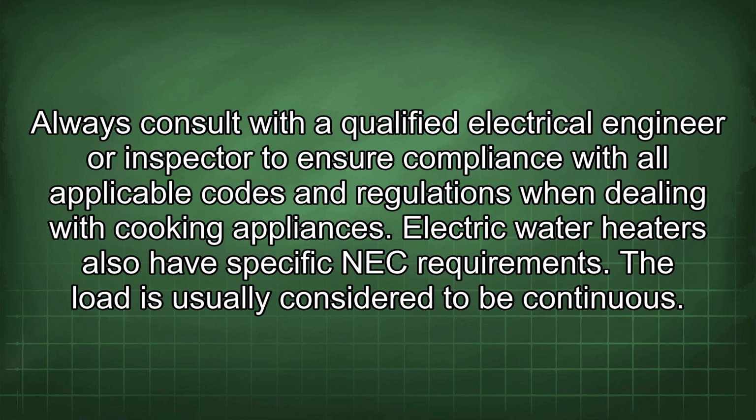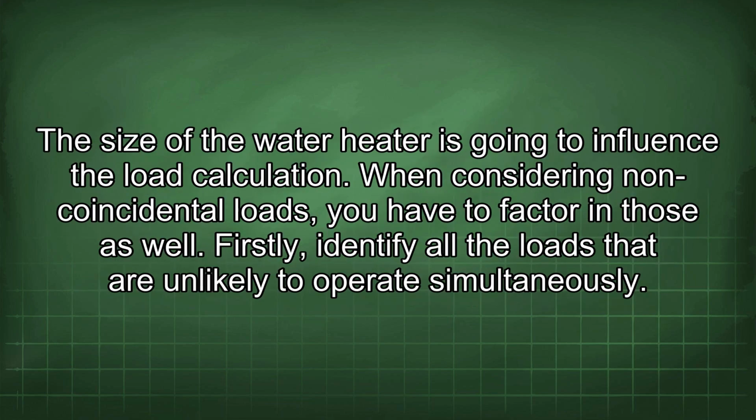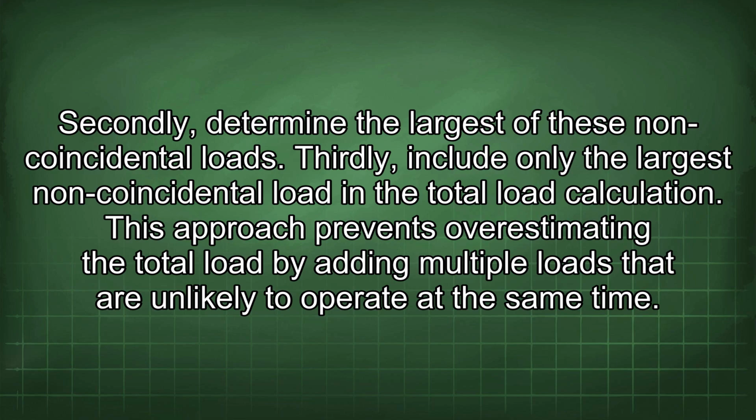The load is usually considered to be continuous. The size of the water heater is going to influence the load calculation. When considering non-coincidental loads, you have to factor in those as well. Firstly, identify all the loads that are unlikely to operate simultaneously. Secondly, determine the largest of these non-coincidental loads. Thirdly, include only the largest non-coincidental load in the total load calculation.